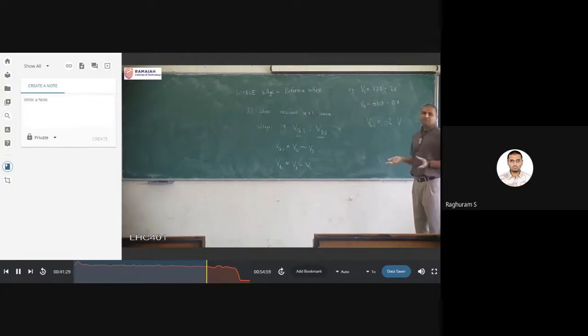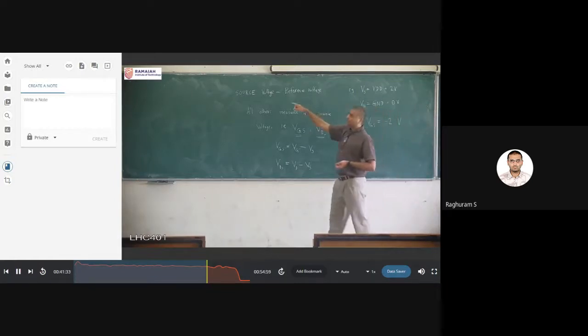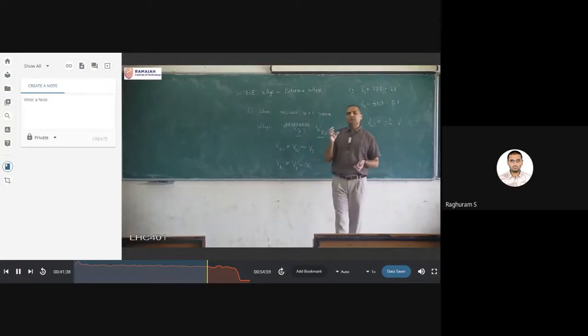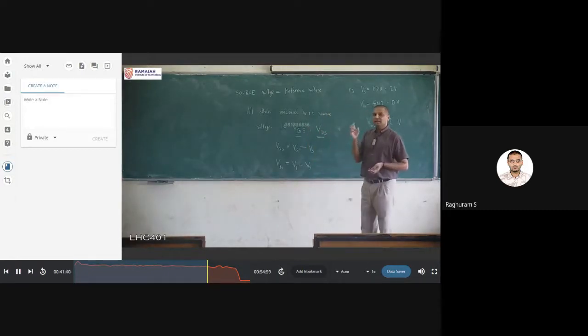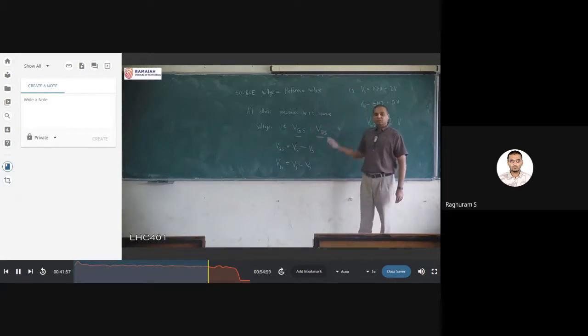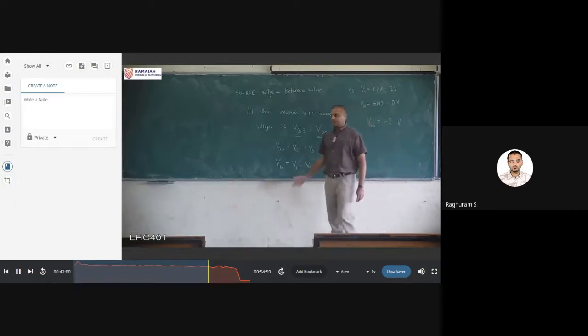But this is the main way. There is no negative source. So this we will follow from now onwards. We will try to measure everything with respect to the source terminal. That is, we have gate voltage and drain voltage. Instead of just calling them VG and VD, we will call them VGS and VDS. So far we have been only working with VGS, right? We have not seen the VDS. Next we will see what is the effect of this drain voltage on the transistor operation.